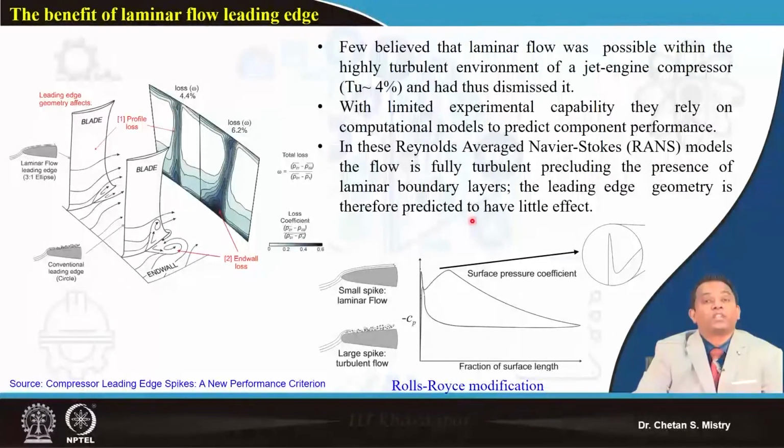So in order to study what is happening on my blade surface, we will be selecting a larger chord cascade. When we have a larger chord cascade, we can capture the minute details of what is happening on my suction surface, and the same way what is happening on my pressure surface.